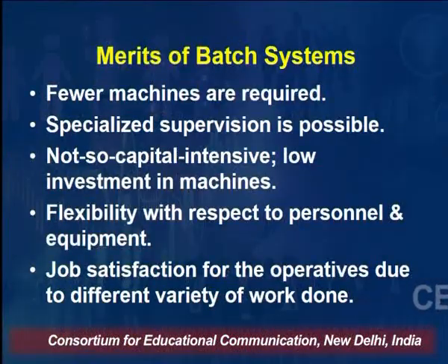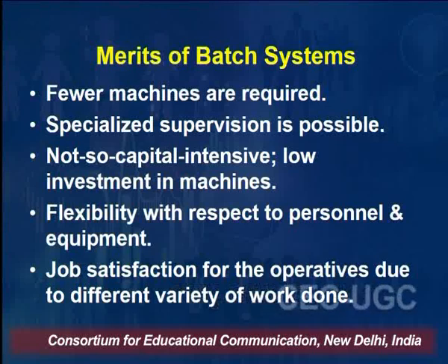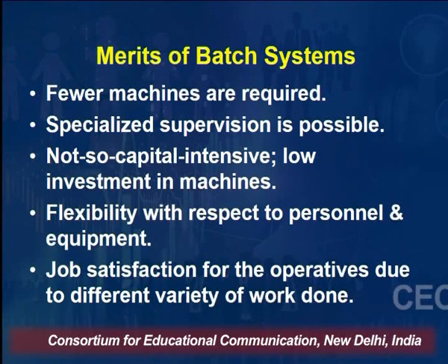So what are the merits of batch systems? Here merits are fewer machines are required, specialized supervision is possible, not so capital intensive, low investment in machines, flexibility with respect to personnel and equipment, job satisfaction for the operatives due to different variety of work done. So what was the demerits of a continuous process systems becomes the merit of a batch production system.